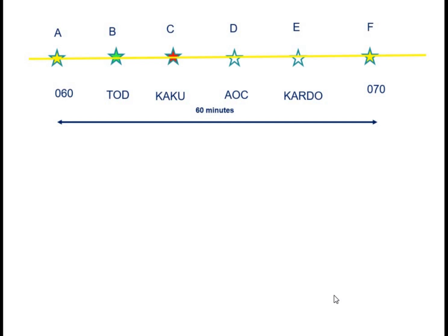At point D, no report will be sent to air traffic control, as this point was inserted by the pilot to trigger a report to the air operator's control center. Also, no report will be sent to the air traffic control at point E, since there is no intention for any change at this waypoint.